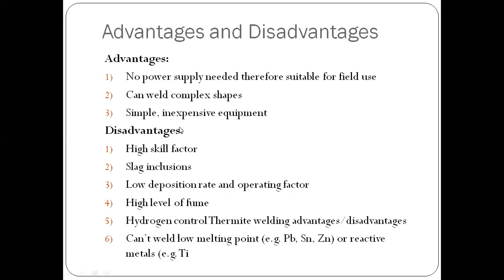process, the thermit welding process. And apart from railway track welding, for other complex shapes, suppose we have a permanent die of any casting, right? You have a permanent mold, and you have been using it for casting several small castings, for large scale production. Due to some reason there is a fracture, or your die breaks into two pieces. Then you can again use this kind of welding process to join that die.